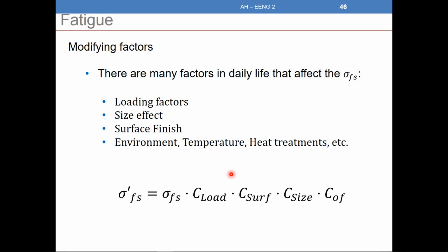There's another part here, the fatigue limit: the stress under which even if I do it infinity times it will not break. It also depends on some other factors, so it can change depending on the load, because what we did is about a tensile load only, on the surface finish, the size, and other factors, depending on the temperature. So it's not very important for us. For us, it will be given directly, the sigma fs or the sigma prime.